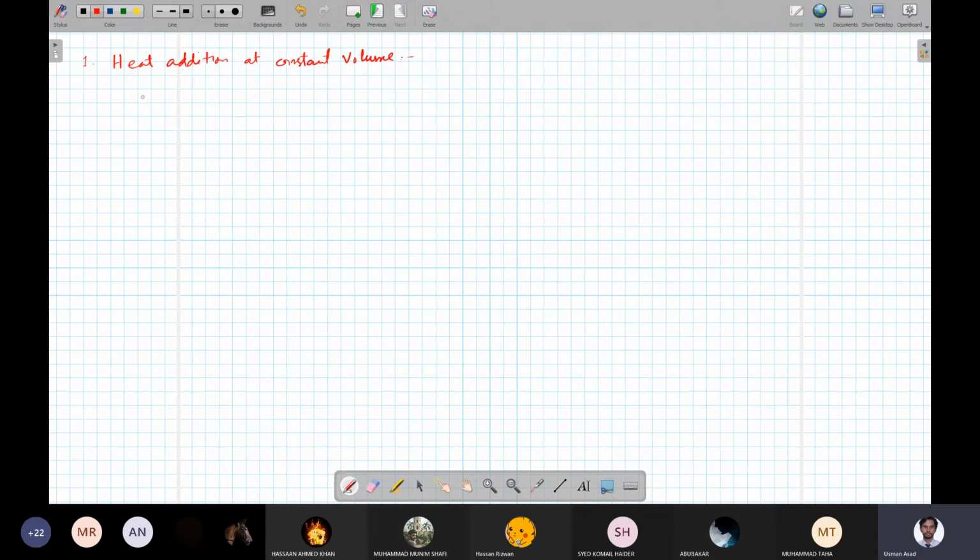ठीक है. अब उसके ऊपर you're doing an energy balance, so the energy balance says कि delta E is equal to Q12 minus W12. But if you're talking about a stationary system, this delta E becomes delta U, right? If kinetic and potential energy effects are not that important, mostly internal energy का फर्क आ रहा हो. So this is what it becomes.